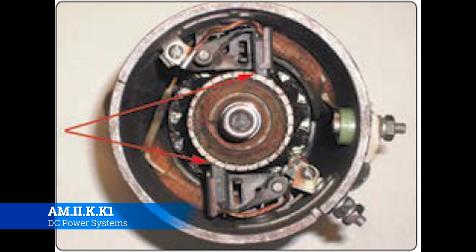to pay attention to. Whenever you reinstall it, you're always going to want to do a maintenance operational check, or MOC. You're going to hear me start using that a lot more. Make sure that you're getting the power that you need from the cockpit standpoint. Go up there and check it, and we're going to go over the Max's DC power panel, so you can know what right looks like there. But also go back to the generator itself as the engine's running and it's moving, and just listen to it. If it sounds like there's something not right, then there's something not right, and you need to address that. If you notice any sort of movement or sparking or weirdness, then shut down and start trying to investigate what's going on there.